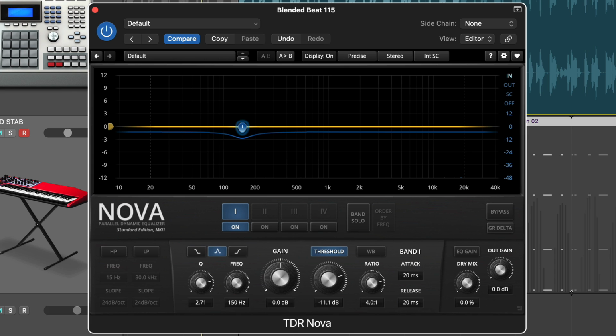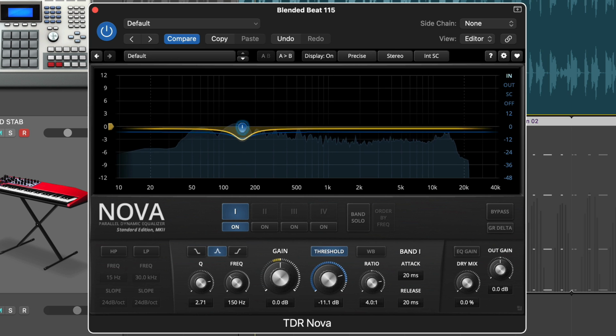Although we typically use dynamic EQ to compress, many of these processors also include upward expansion. This results in a boost to specific frequencies at the set threshold. On this plugin, this is achieved simply by selecting a ratio lower than 1:1. Sticking with our existing settings, adjusting the ratio to the minimum setting, 0.5:1, achieves a frequency-specific boost when the threshold is exceeded.